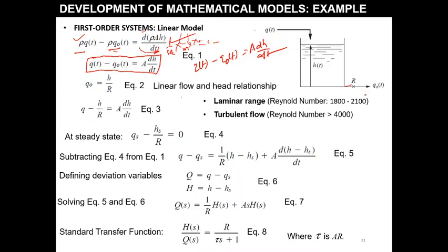Now come to this part. I already told you this is the valve, and the valve is used here as a resistance. It produces some resistance. This is for the control of the flow. So this is the relation between q naught, h and R, because ultimately this R is going to change the height and the flow.